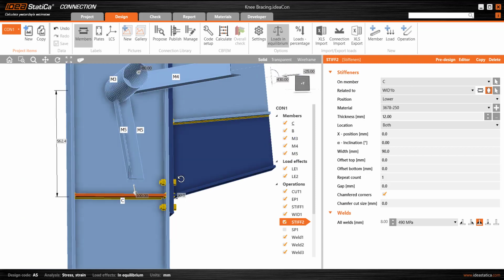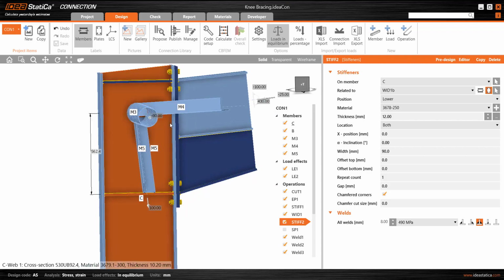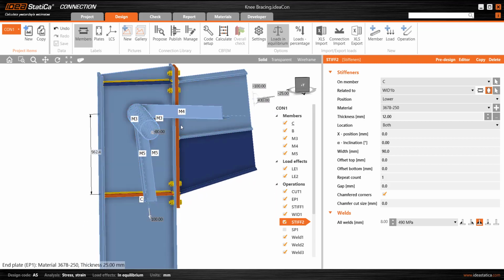value there. So this type of method of making sure we use the relative operations to position things as far as possible is highly recommended, because it makes the entry simpler and quicker, and also more adaptable if the rafter size changes here, or even the column size, because we're on a little bit of a slope. The stiffeners will adjust vertically as necessary with this arrangement.